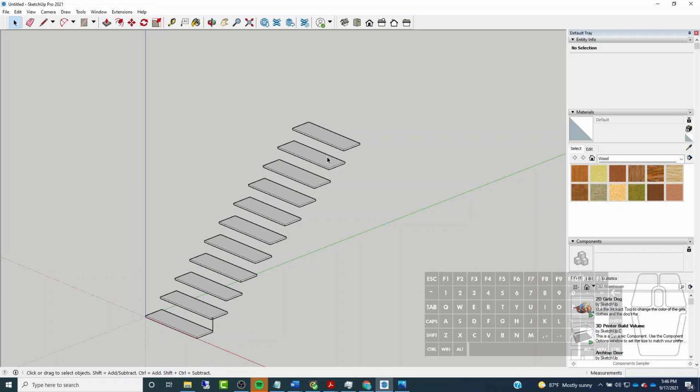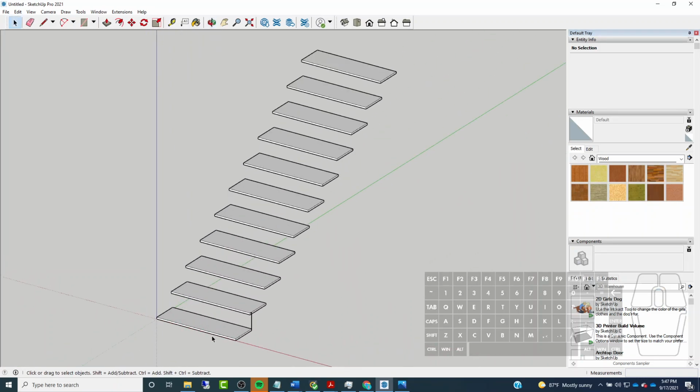So sometimes when you're trying to make a flight of stairs, you'll get a bunch of errors because everything is constrained and things will start to break when you're moving things around. But if you know how to do everything within SketchUp like this and model all the components of these different objects, like stairs, for example, you have the opportunity to do a lot of really custom stuff that you just can't do in Revit, which is really nice.